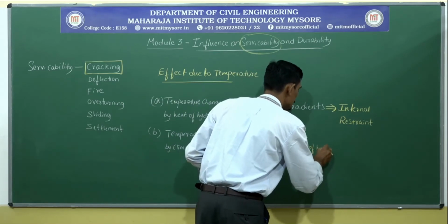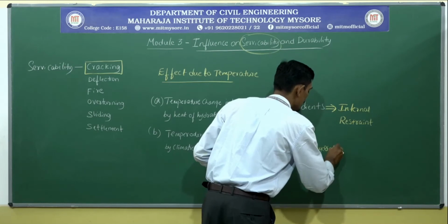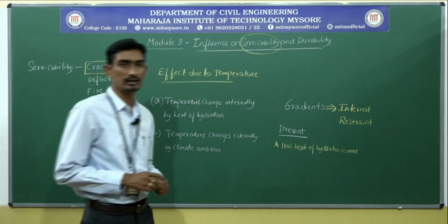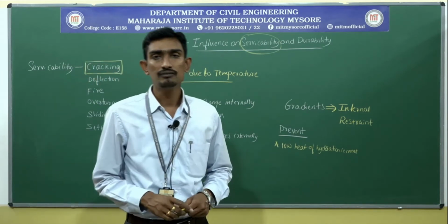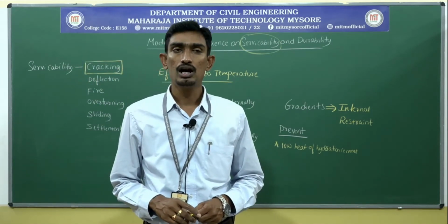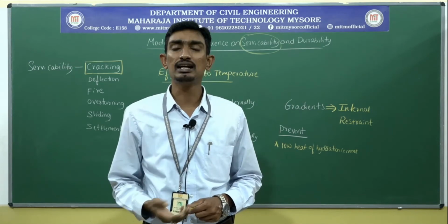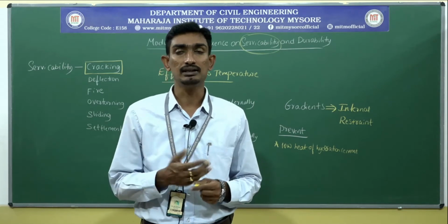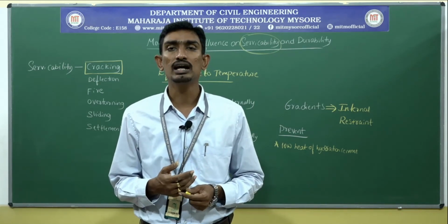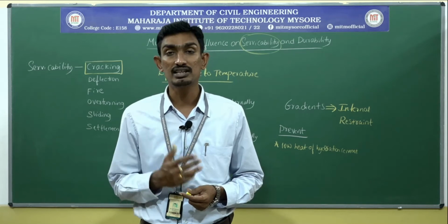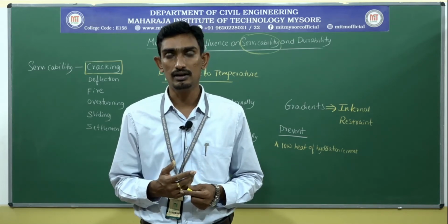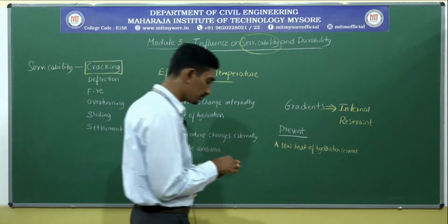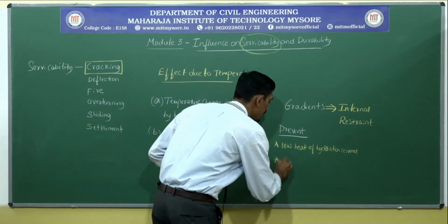Low heat of hydration cement. So that is the first point we can go ahead with. By using low heat of hydration cement, we can prevent this. And also by using a supplementary cementitious material, that is blending fly ash with cement, there also you can arrest the temperature difference cracks developed internally. And the next point, we can do something like pre-cooling.